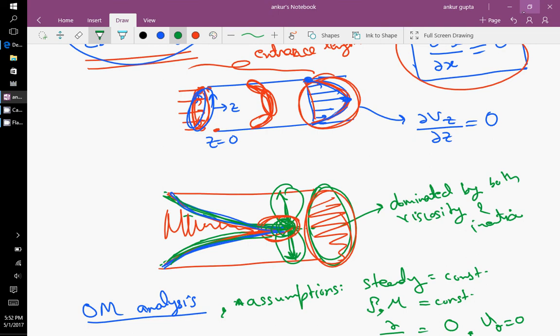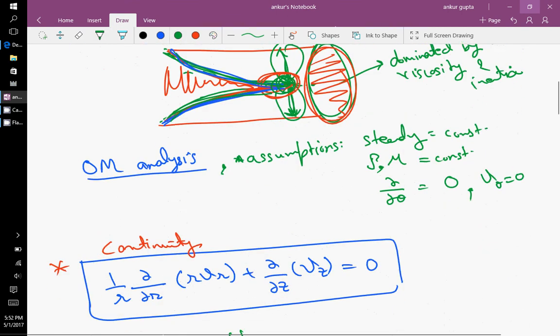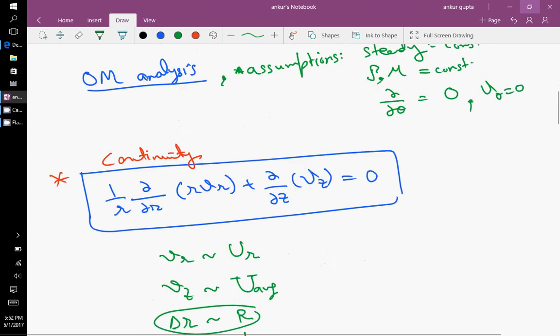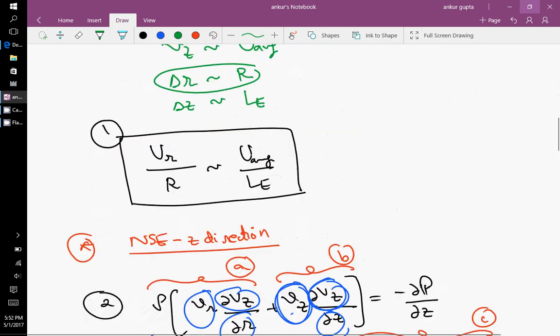When the boundary layer becomes half the distance between the two plates, or becomes equal to the radius in the case of pipe flow, the velocity will no longer change with distance, and that is the condition we wanted to find, when both sides meet and the whole region becomes fully developed.